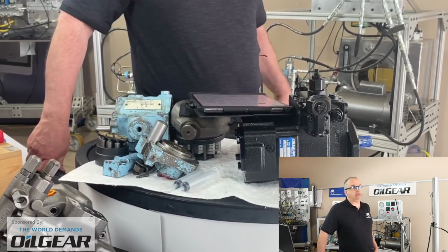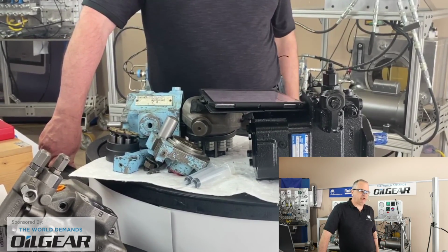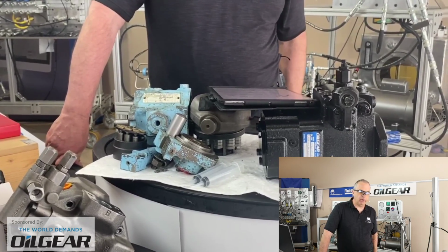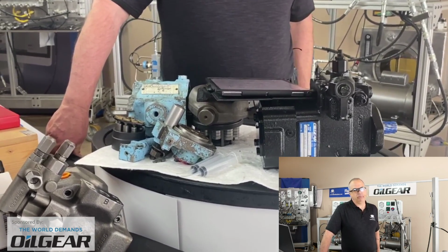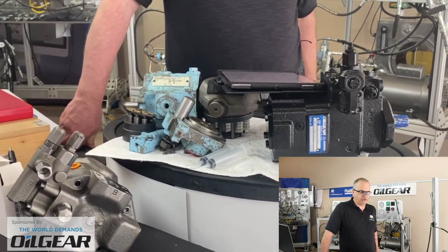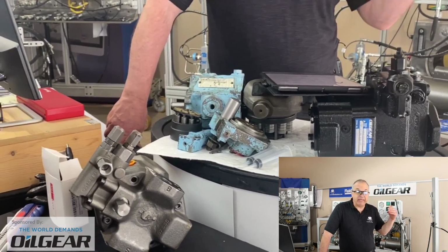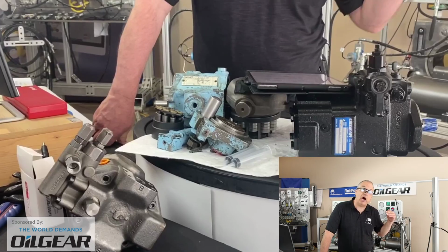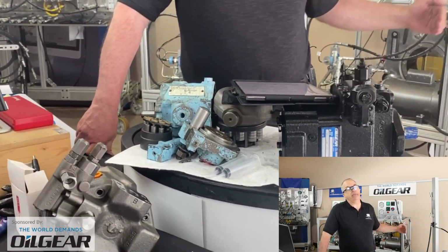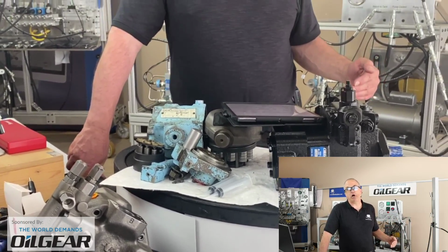If you can detect the condition of a pump by its case drain flow, then quite often you're at five seconds to midnight, and there have been many other golden opportunities to measure, such as volumetric efficiency testing on a piston pump. But there have been times when observing case drain flow and finding out that it was unusual compared to an identical pump sitting right next to it has been a clue for us to dig in on a problem with a pump.